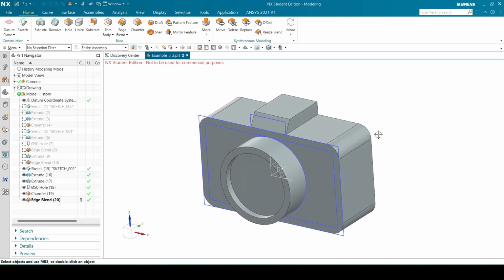So sometimes when you change a sketch after you have already extruded and done stuff like that from that sketch, you should just go into the extrude and make sure it is still fine, because sometimes it wants to change. So you should just check that, in case.